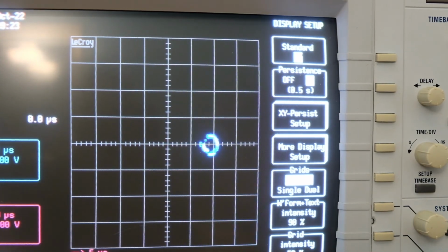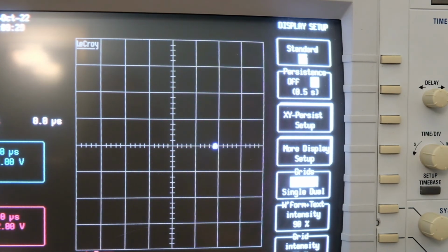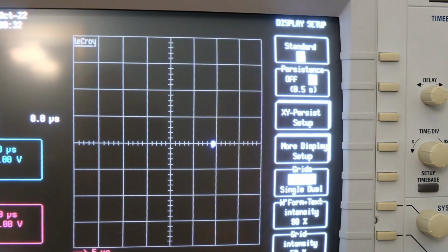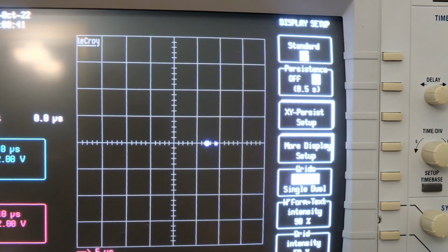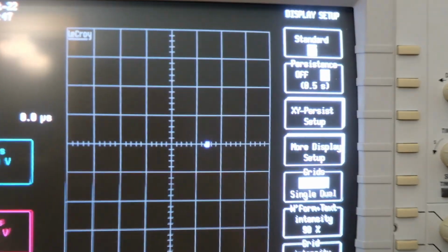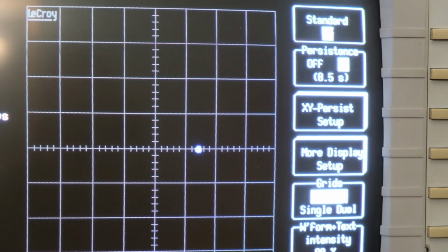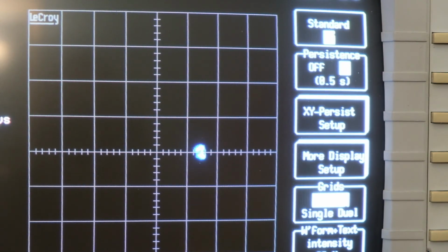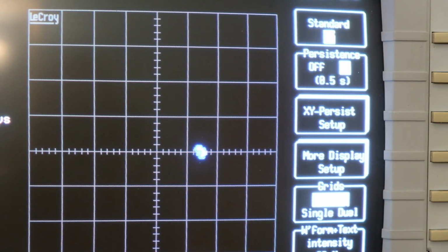Now I'm going to turn on the higher order filter, the longer time constant filter at 30 milliseconds, and this is without the noise. It's now pretty much clean, and now with the channel 2 noise added, while the amplitude changed a little bit, it's very, very quiet as before. So the filter time constant is very important. Changing it back to 1 millisecond, 3 milliseconds, 10 milliseconds, and 30 milliseconds.